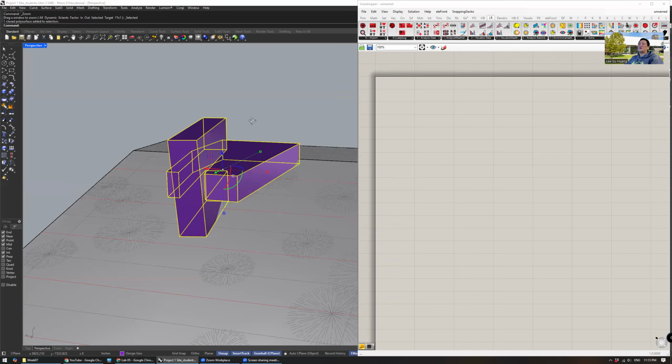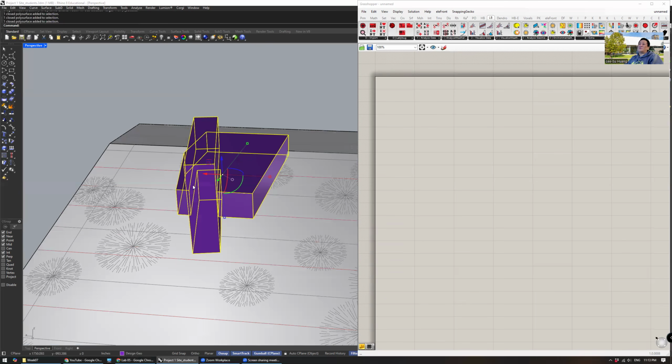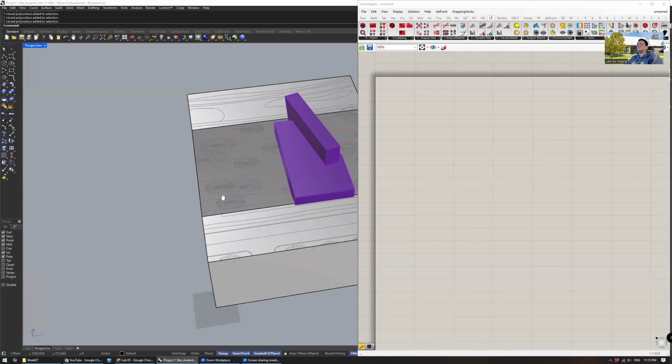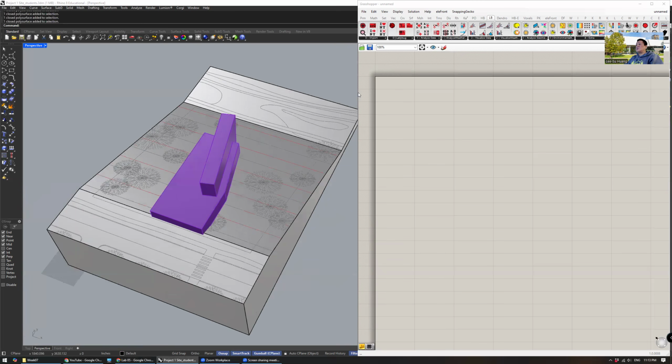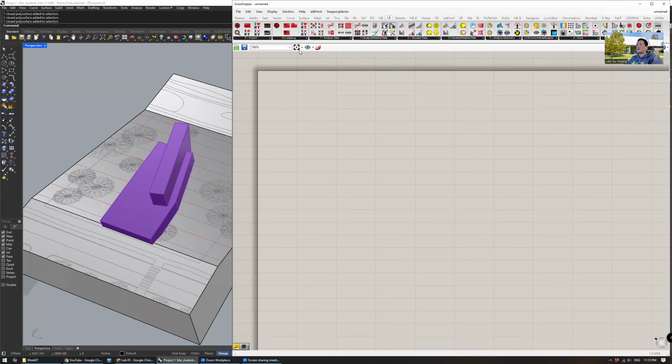And you'll notice that ideally, right, this is simple massing, no windows, right? No kind of weird projections, and don't get too granular with it. It'll just make the simulation calculation take much longer. And then ideally Boolean union them all together into one single poly surface like this. Okay. All right.